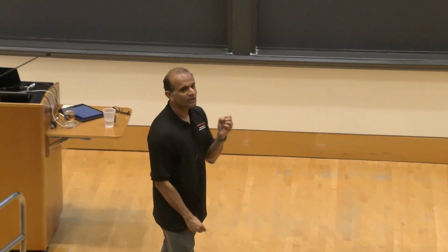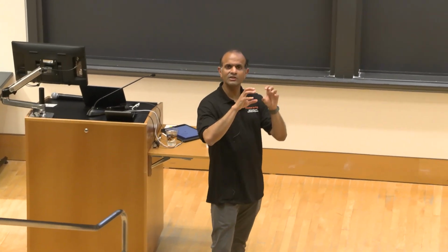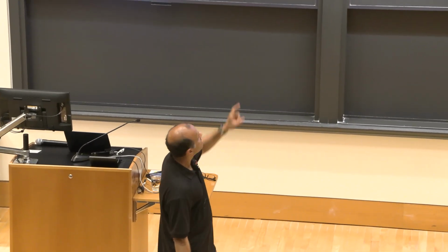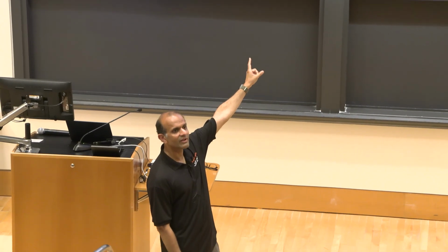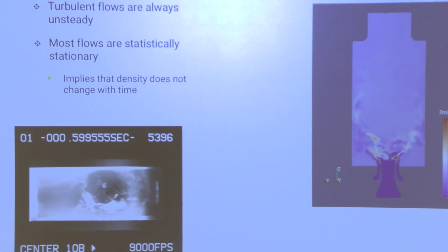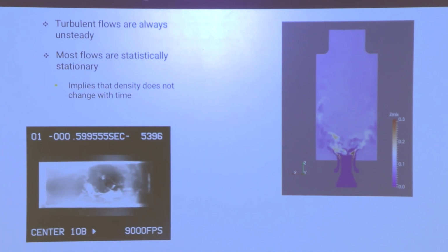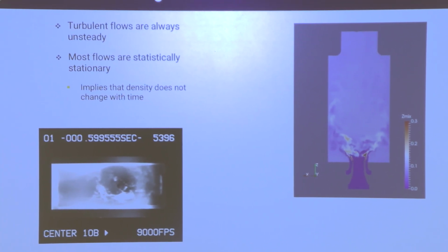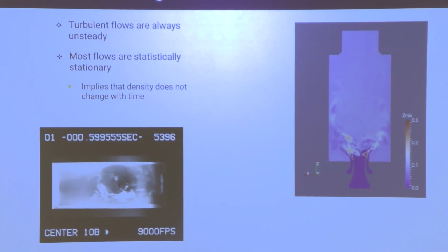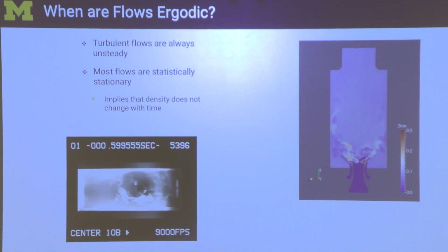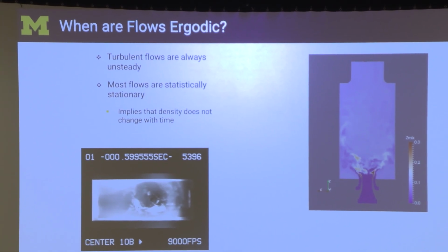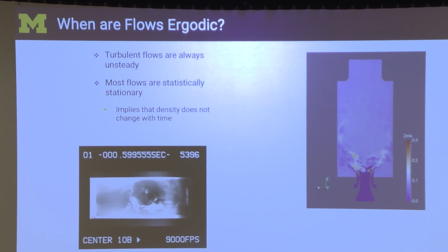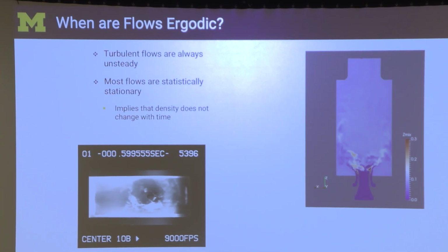So even though we think of turbulence as some kind of continuous perturbations, soot and these kinds of features are very intermittent. They are not there all the time. So if you make measurements for a very short window, when there's no soot present, you will conclude that soot is not formed in this reactor. At the same time, if you average for a sufficiently long time but capture more of the times when there is a lot of soot, you will also inaccurately claim that there's a lot of soot being produced here.